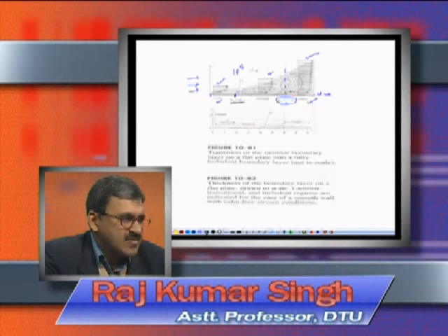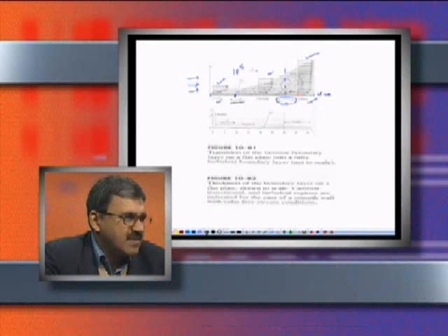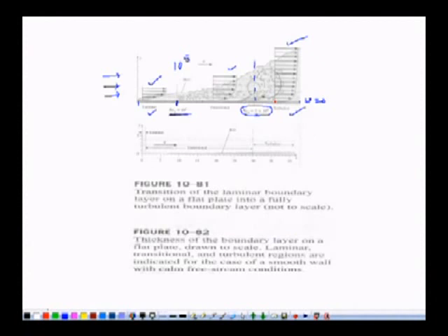V is equal to 0 to satisfy the no slip condition. As we move away from the solid surface in the transverse direction, the velocity is large. If velocity is large, then the gradient is very sharp, very high. That's why in case of turbulent boundary layer the shear resistance is also very large, right.